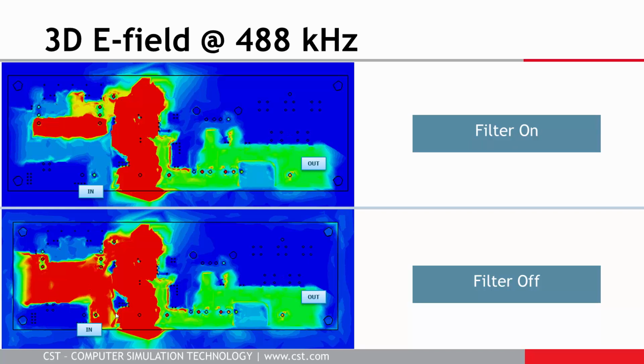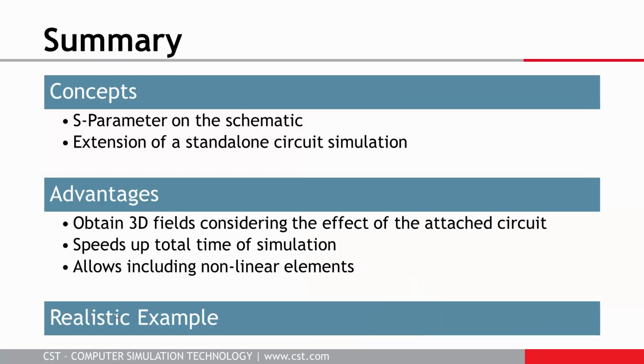So let me summarize today's webinar. I have shown you the concept of coupling a 3D simulation and a circuit simulation by using S parameters on the schematic. There are a few new things that you need to learn, because such a coupled simulation is an extension of a standalone circuit simulation, and the use of the ground symbol is a little bit different from what you are used to in SPICE simulations, but I'm pretty sure that it is not too complicated to learn.